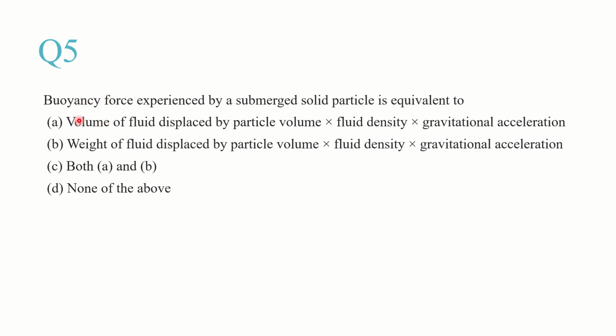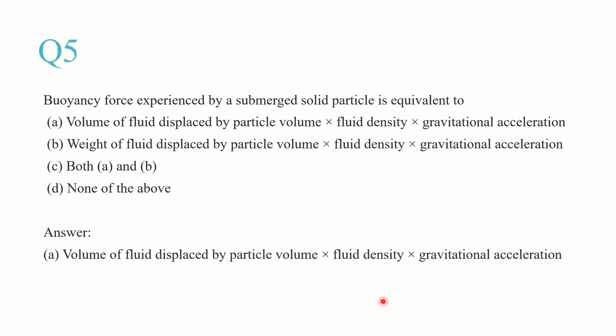Rho is common in both options, that is the fluid density, and gravitational acceleration g is there too, multiplied by V, the volume of the fluid displaced by the particle volume. So the answer is option A, volume of fluid displaced by the particle volume into fluid density into gravitational acceleration.